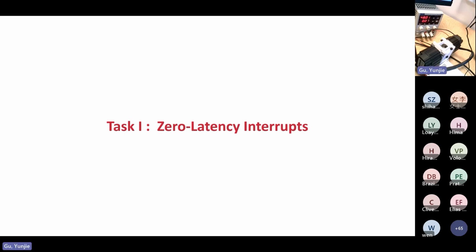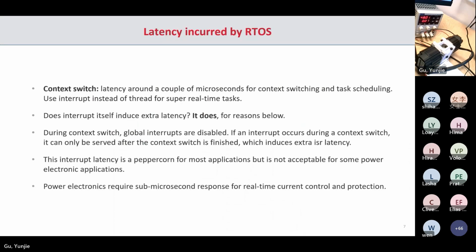The first task is to address the challenge of zero latency response. We know that the RTOS introduces latencies, and the most well-known one is the context switch for threads.